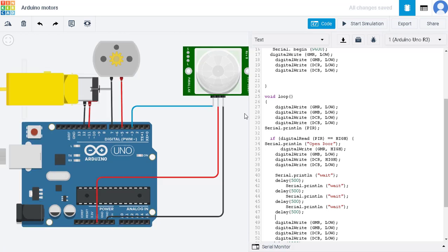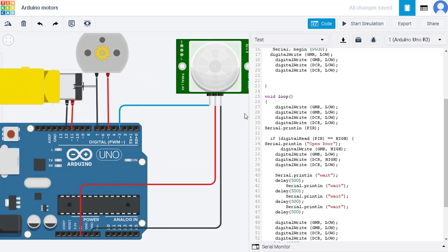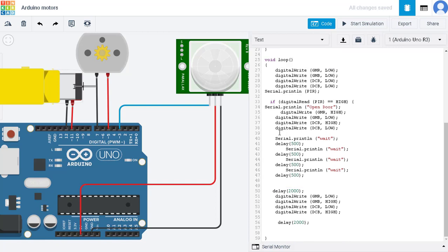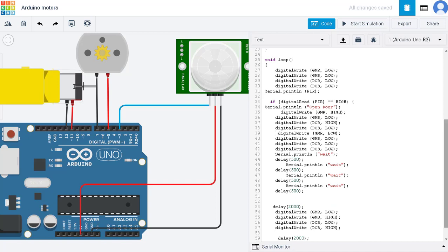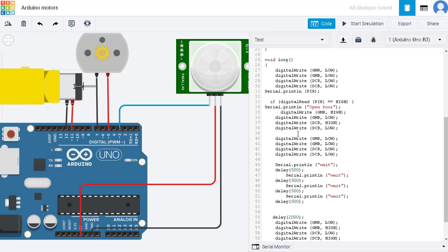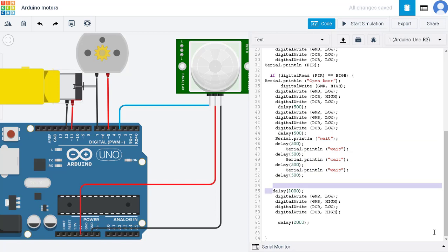because I first open the door, the second part of the message is that the door is not going to move or the motors are going to be stopped. So I am going to copy these digital writes for the four motors all in low or in high, and this means that the door stops, and then is when it is going to appear the message of wait. I'm going to give a delay between one command and another. That is something important. What I have now is the door open, the door stops, and while the door stops, shows the message that is waiting.